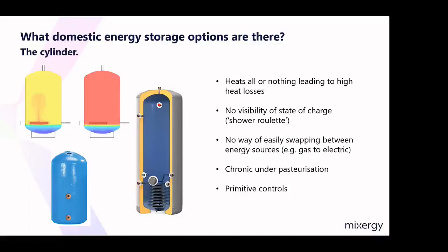Water is heated from the bottom. The whole tank has to be heated to create usable hot water or to pasteurise for Legionella. Water is great at convecting. Lots of hot water is created above the heat source, but water is a poor conductor, so we're left with a grey area of water below the heat source, which never reaches pasteurisation temperature, which creates a problem for water hygiene policies.